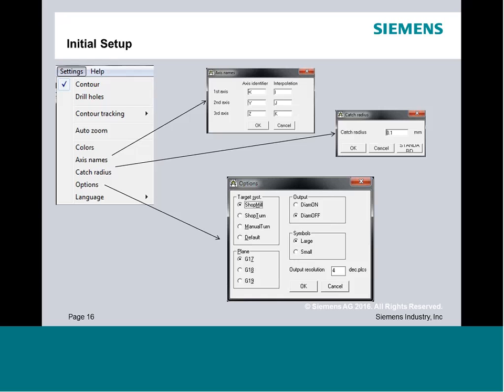So what happens here is if you have a very large value, you might find that this is starting to kind of merge lines and features together, and it's all because it was left at a default value that would be appropriate had this been a metric scale drawing. But if it's really an inch scale drawing, now it's just this huge value. So you are going to want to go in and reduce that. I would say a common number here might be a couple thou. That would be a standard value that you would use.